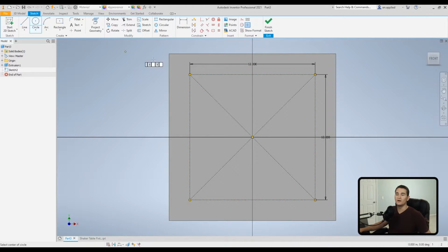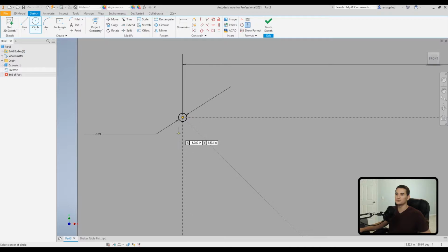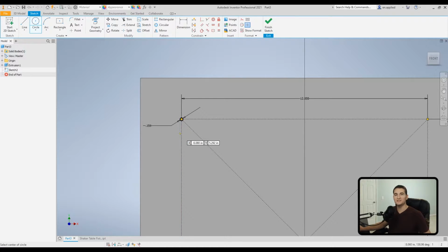Okay. Now our hole size, I've got it written down here. It needs to be 0.159 inches. So this is for our 75% thread for aluminum, which is our material in this case. So I'm just going to pick up this corner spot here, set my hole size. And these will eventually be threaded. So this is the pilot hole size for the thread, just for you folks out there that are wondering why I picked this size. If you're unsure of what your thread sizes should be, make sure you check out the tons of free drill charts and tap charts online. There's plenty of good information out there with this info in it.